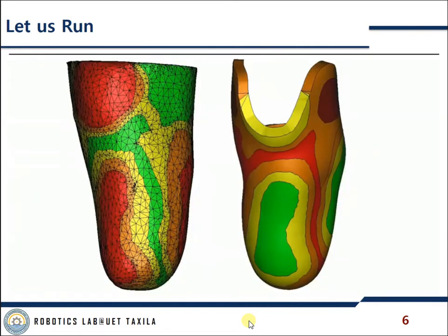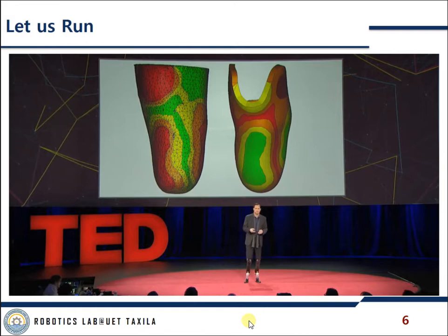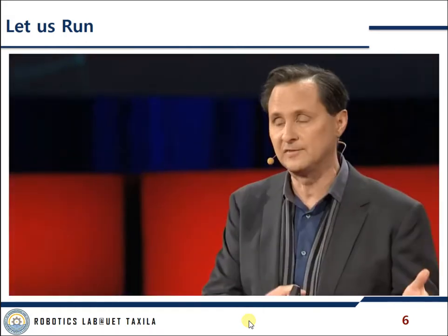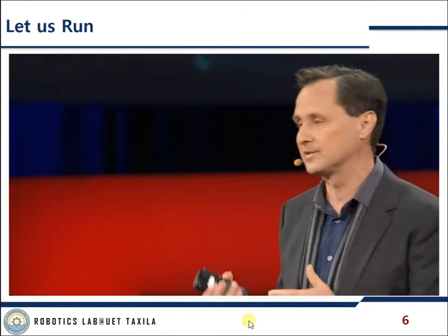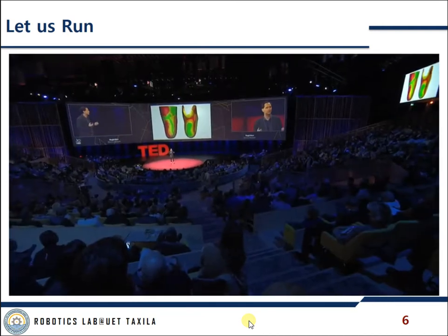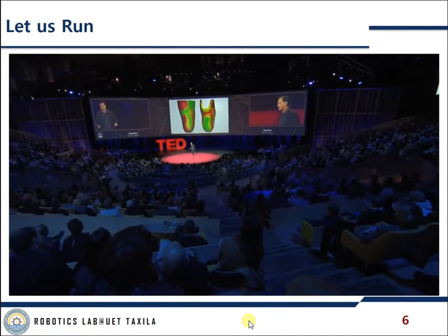We combine these imaging and robotic data to build a mathematical description of my biological limb, shown on the left. You see a bunch of points or nodes. At each node, there's a color that represents tissue compliance. We then do a mathematical transformation to the design of the synthetic skin, shown on the right. And we've discovered optimality is where the body is stiff, the synthetic skin should be soft. Where the body is soft, the synthetic skin is stiff. And this mirroring occurs across all tissue compliances. With this framework, we produce bionic limbs that are the most comfortable limbs I've ever worn.